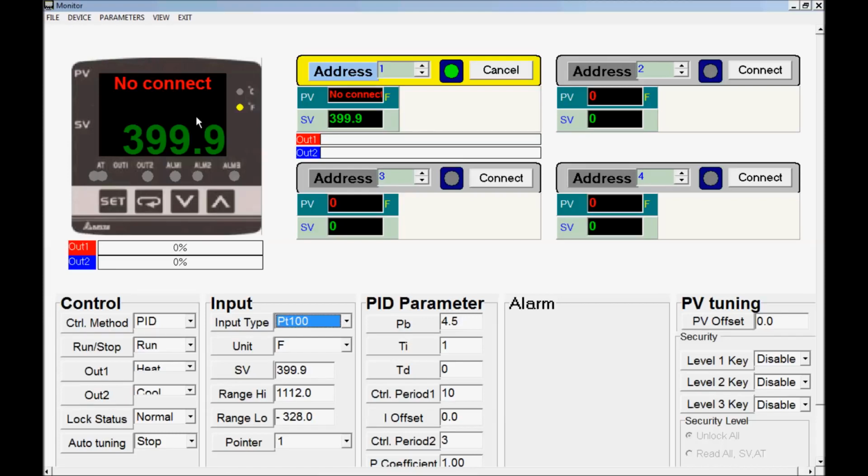But if you have this up there, odds are you have an error, the red LED under error on, so you'll know ahead of time anyways. So I'll go back to K-type here, and you can see the temperature comes back up.